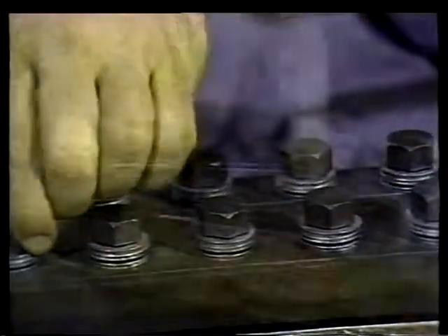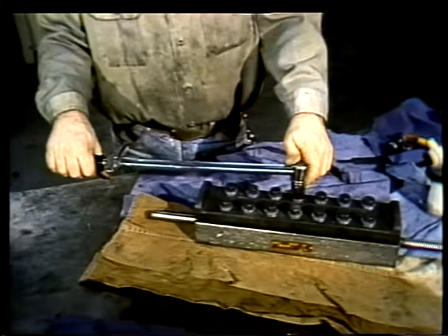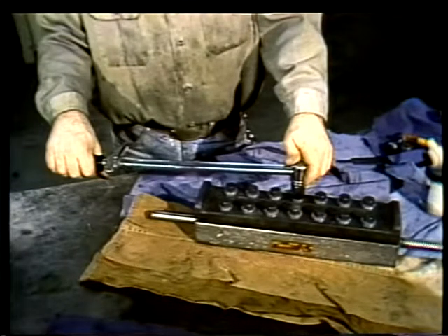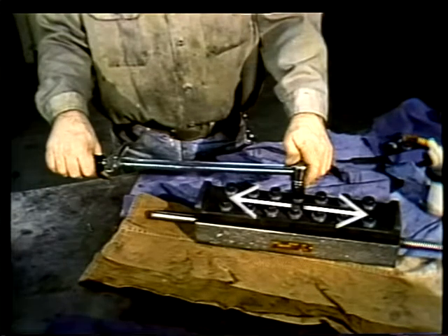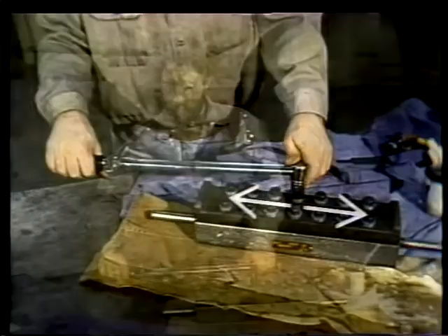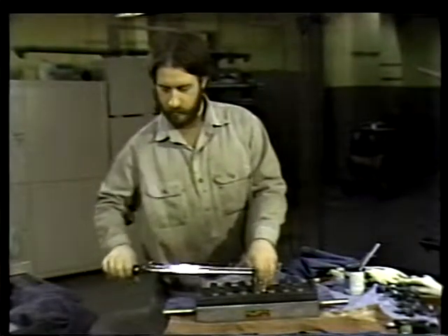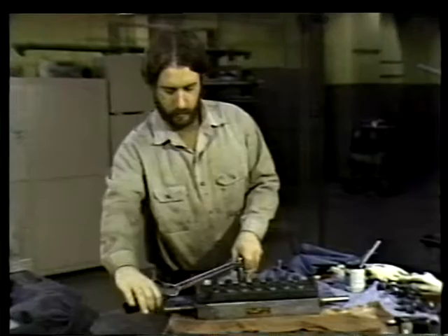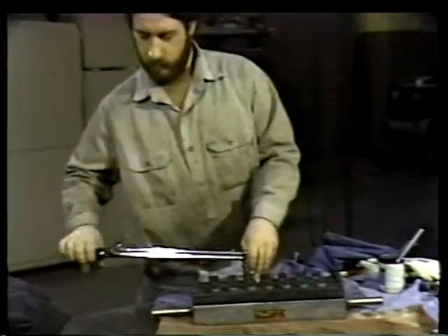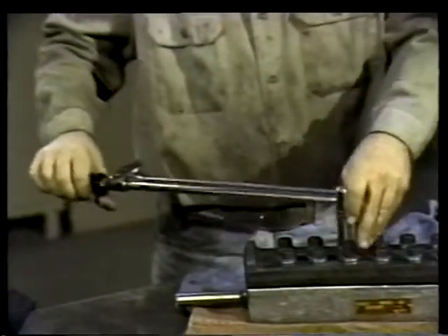Then, using a torque wrench, tighten the bolts to the manufacturer's recommended torque. Follow the same tightening order as before. Start in the middle of the gauge and work outward, alternating in both directions. Start with about 1/4 of the recommended final torque and go over all the bolts again. Final torque should be reached in about 7 passes. Use the same procedure to install the other cover plate on the gauge. Once both covers are in place, the gauge can be returned to service.